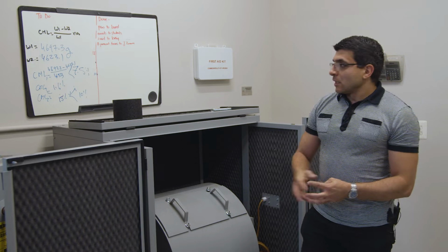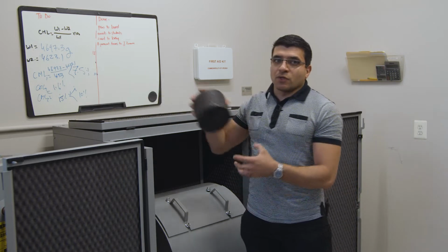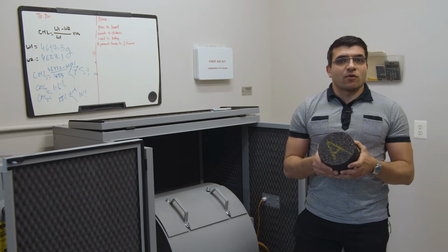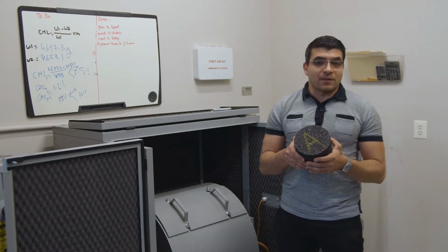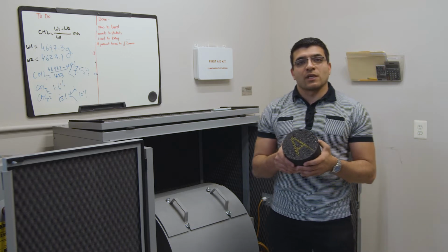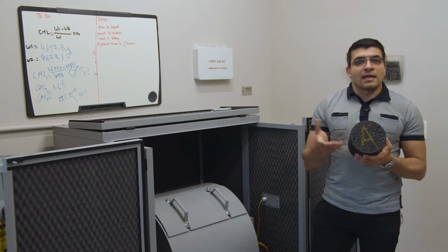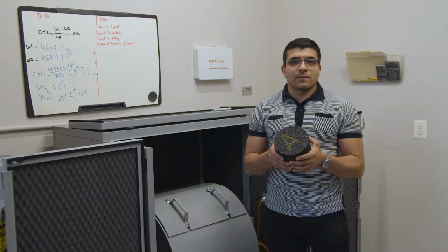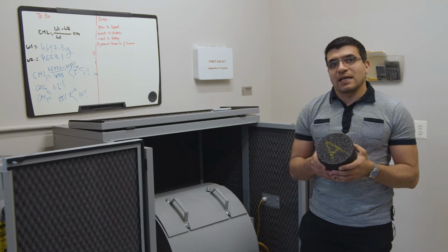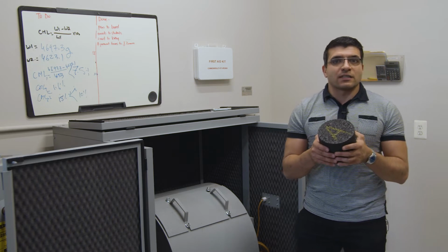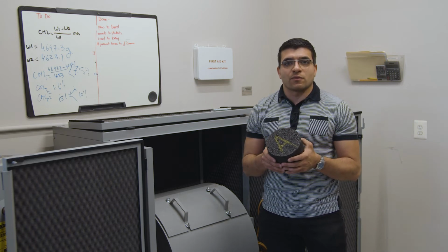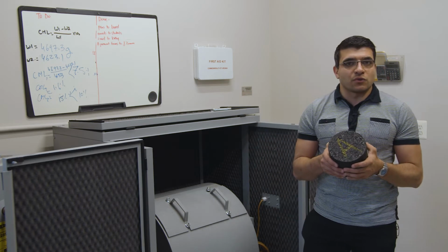thermometer. Our specimens are usually design pills with a diameter of 150 millimeter and a height of 115 plus or minus 5 millimeter. These are usually lab compacted specimens, but could be as well taken from pavements, also known as cores. For lab compacted specimens, these could be mixed in the lab and then conditioned for 2 hours at the compaction temperature, then compacted to a height of 115 plus or minus 5 millimeter according to SuperPave.